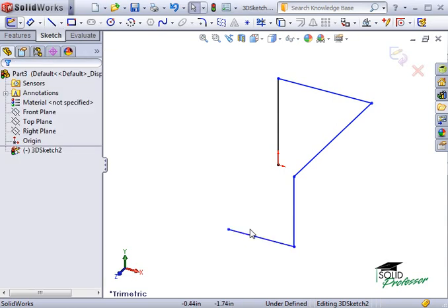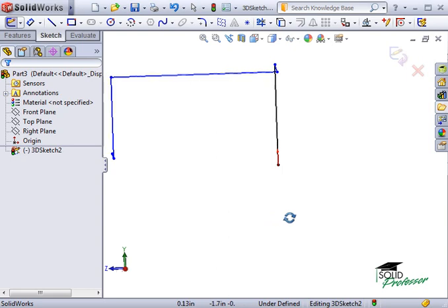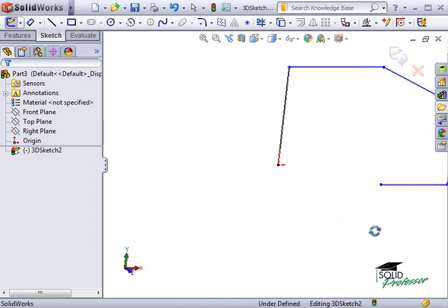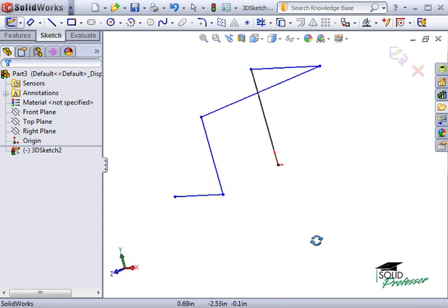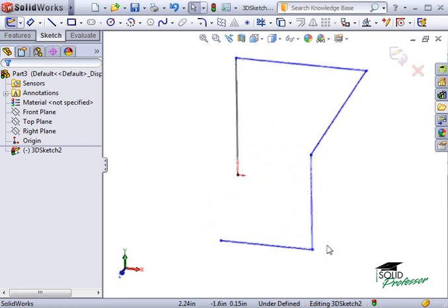You can see as I rotate the sketch that I've got a 3D structure that could not have been created using a 2D sketch. In fact, to create this using 2D sketches, it would have been necessary to create two reference planes. Although what I've shown you so far may seem very basic, I do recommend you try using the Line tool along with the Tab key to create some basic 3D structures like this one.